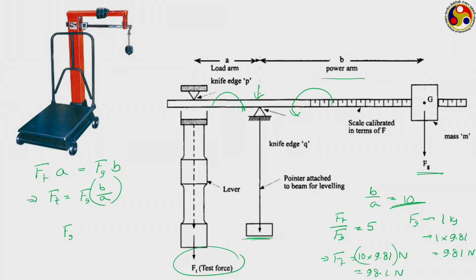So, when you are looking for very large quantity of force measurement, that is, we are dealing with a very large value of this Ft, this particular point is flexible. We can move this particular point along this particular scale in either left or right direction, thereby changing this ratio B by A as per our requirement, and we can get quite large range of Ft to deal with.